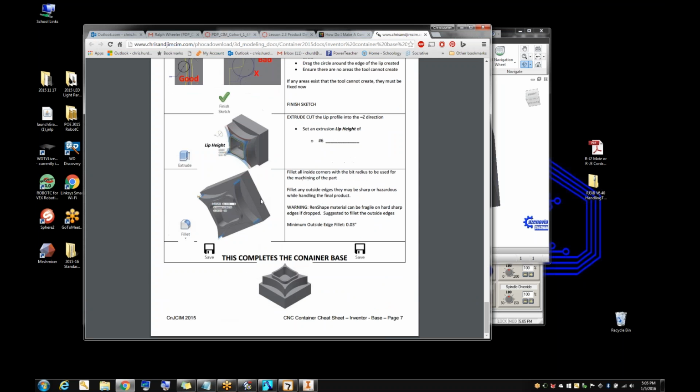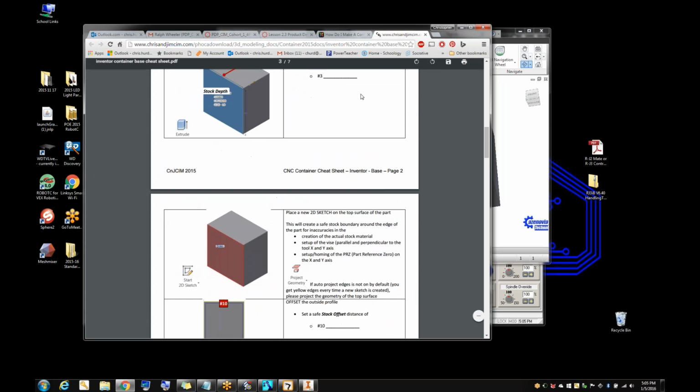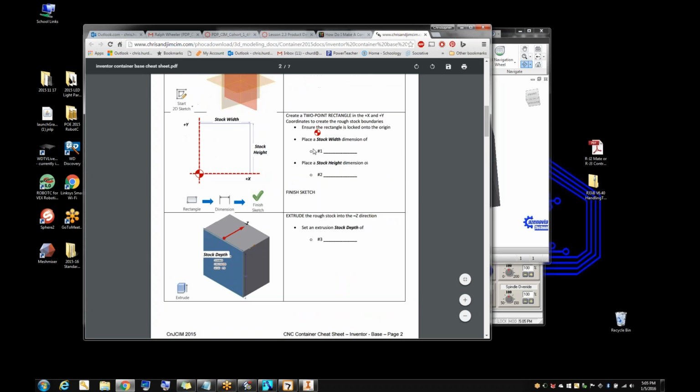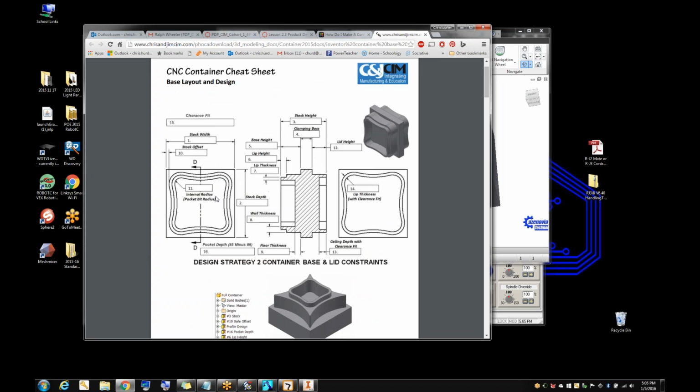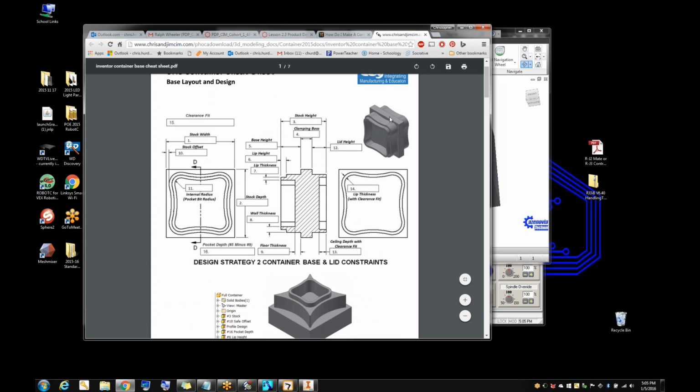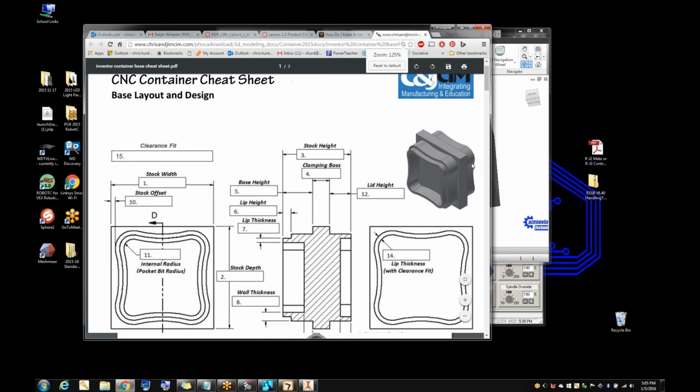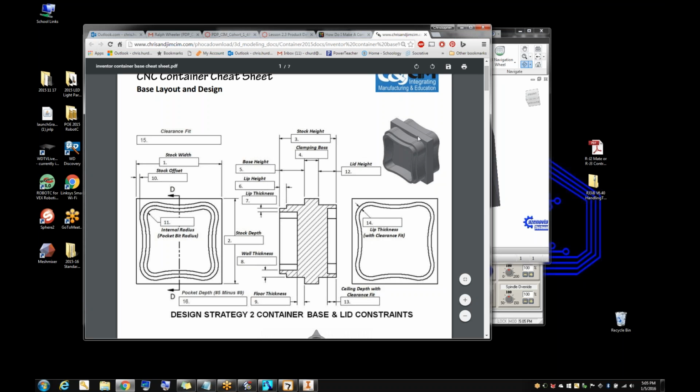Okay, I think I just realized what I was thinking, Ron. I want this container, the part we're milling, I actually want it to be above the vise. Correct. Yes. It's not above the vise, and you lose part of your vise. That's what this boss is. Yeah. Right. That's why I was thinking it had to be a 1/2-inch border around it, so you didn't lose the vise. Right. But that's what that big rectangle in the middle is for. Yeah. Okay. And then the rest of that should stick up above the vise. Yep. Yes.